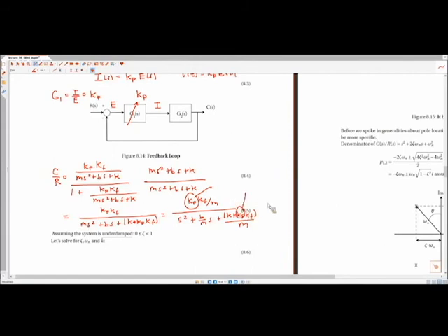And so to change how the system behaves, if we look at the s to 0 term, this corresponds to natural frequency, right? So we can actually change the natural frequency of our system just by changing a line in code, recompiling, and running again. So it's a very quick, easy way to change how a system fundamentally behaves by just tuning something that's really inexpensive to change.